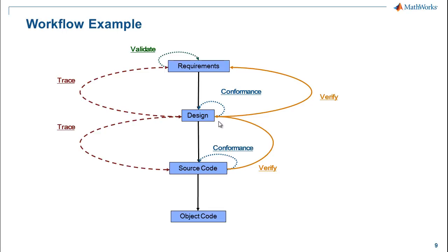And to do that, we need to compile it, right? And I break this out as a separate step because in a process like a DO-178C level A process, this compiler step is actually very important. There is a difference between me, say, compiling locally and running test cases on my desktop versus me compiling with an IDE and actually putting the object code on the target processor.